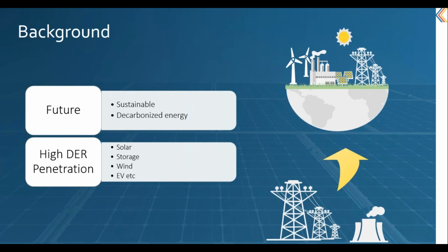However, decentralizing the electricity grid introduces a whole lot of new instabilities in the grid. For example, with the conventional approach, whenever a local fault, a voltage spike, or any other disturbance happens in the grid, protective circuitry quickly shuts down all the energy sources to isolate the fault. However, this will lead to cascading system-wide instabilities on a system with high intensity of DER. So, it's important for DER plants to automatically ride through these disturbances rather than simply shutting down.